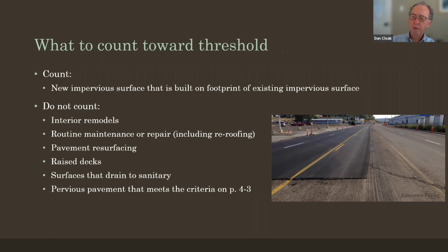Raised decks are out. Anything that drains to the sanitary system and doesn't go to stormwater, those areas can be excluded. And then when it comes to pervious pavement, the key thing to understand is that if you want to put down gravel on top of a couple of inches of gravel on top of clay and drive over it, that does not qualify as a pervious pavement. It's still considered to be impervious.